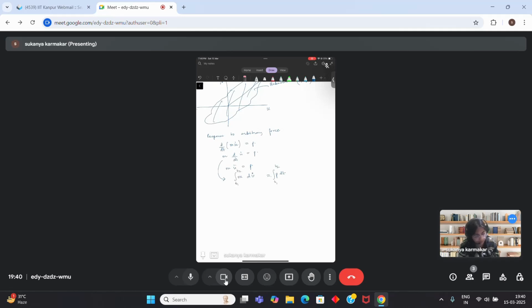Now this term on the right hand side, which is the integral of force into time, is basically impulse, and this is equal to, m is constant, the velocity of the body at time t2 minus the velocity of the body at time t1. So this impulse is nothing but m into delta u dot.